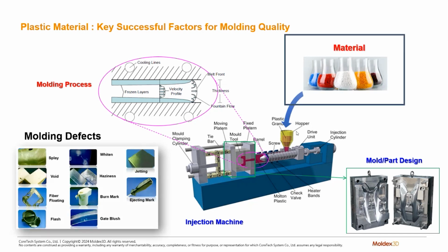So the material properties allow us to consider all the variation in the plastic property that would happen throughout the injection molding process, and ultimately, as it applies to other molding processes as well, like compression molding, like Mucell, like all these advanced molding processes, they hold the same material properties. And from this, we're able to see all of the different molding defects that you might experience in reality.